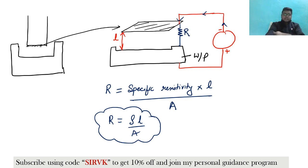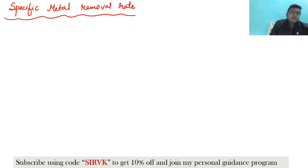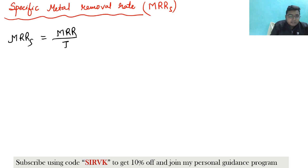So in this context of ECM, there is another terminology that I want to define here, that is known as specific metal removal rate. Basically this specific metal removal rate is denoted by MRR specific, MRR small s. So what is this MRR small s? It is denoted by whatever MRR you are getting, divided by the current. So this is your specific MRR.